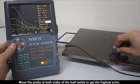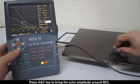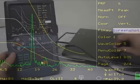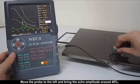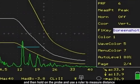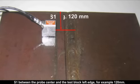Move the probe at both sides of the butt welds to get the highest echo, and adjust again to hit the highest echo. Press AGC key to bring the echo amplitude around 80%. Move the probe to the left and bring the echo amplitude around 40%, and then hold the probe and use the ruler to measure the distance S1 between the probe center and the test block left edge, for example, 120 mm.